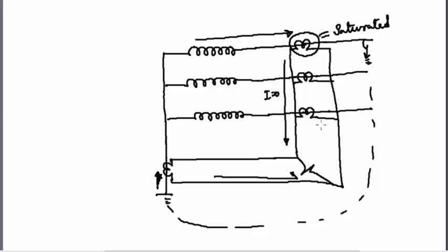Now the only current flowing in the circuit is the current through the neutral CT, and this current is not facing any opposition from the phase side CT, so what will happen? Ultimately it will take up this path, and this REF relay is sensing a current, means now a current is flowing in this REF relay, and the relay will treat an external fault as a fault in the transformer, and it is going to issue a trip signal to the transformer, which is not desirable because the relay should remain stable when there is a fault outside the zone of the CTs.